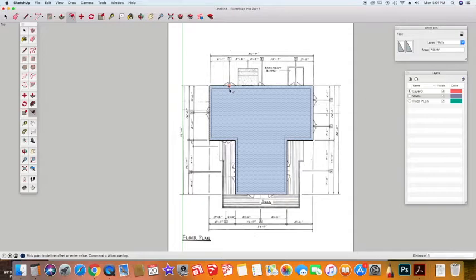And to get inches, you're going to click Shift and then the quotation marks. And you can see that it shows in the lower right hand corner 6 inches, and you're going to hit enter. So right here are your walls. As soon as you do that, you can see that these separate out. If I mouse over it, you can see that these walls are actually separate.